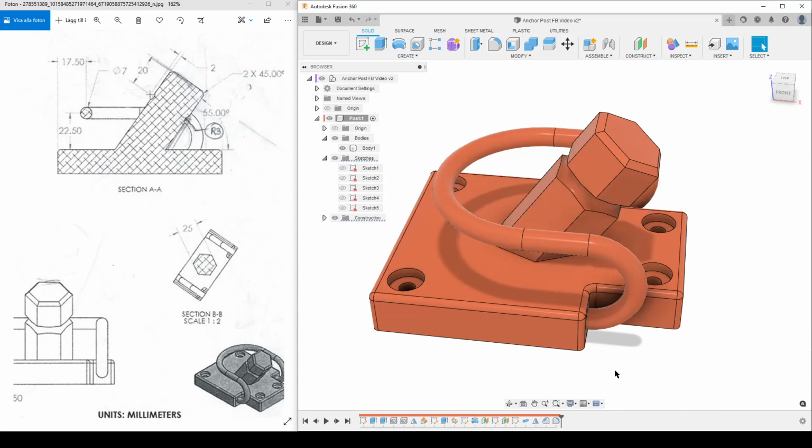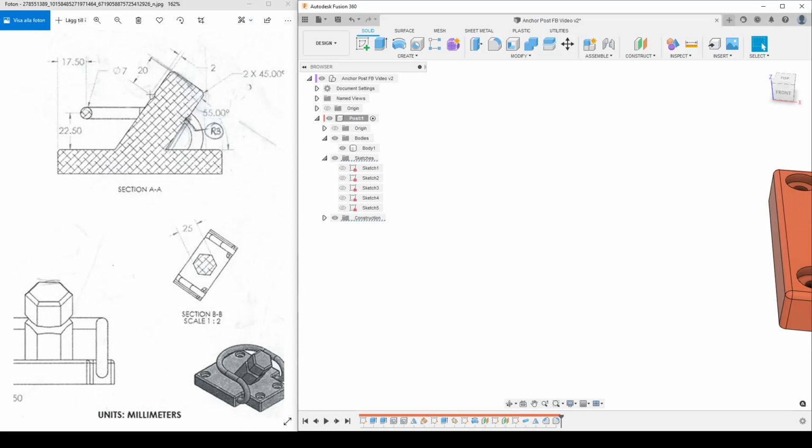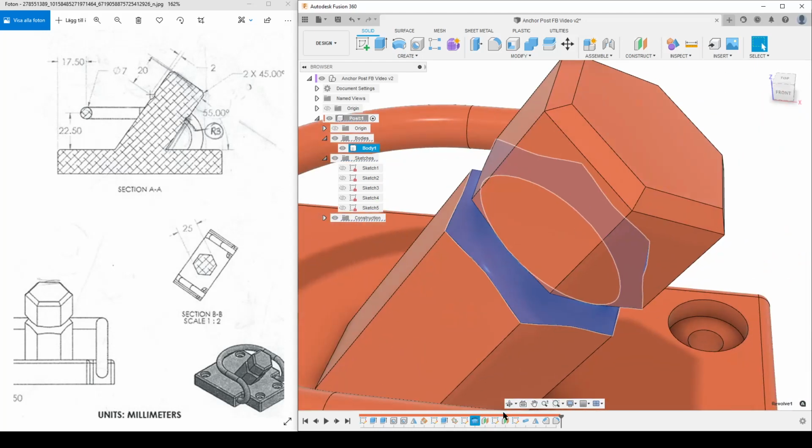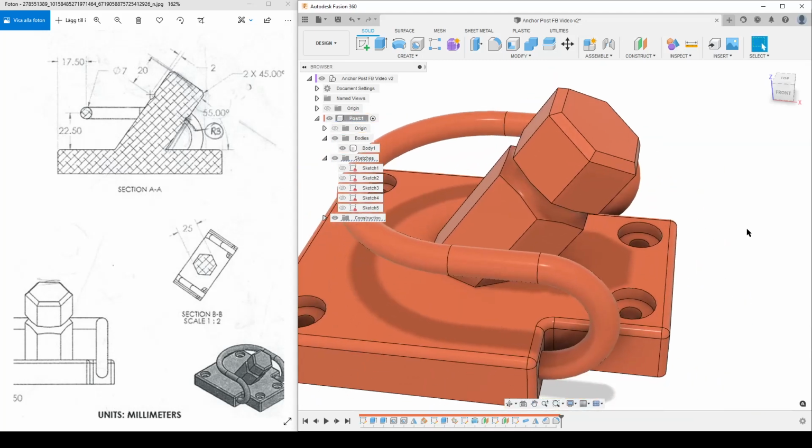And so that's right. That's another thing. If you can't find, you know, this is the Revolve command you want to change, let's say the model, you can't see the face. You can right click on a feature and select Find in Window. And Fusion will zoom in and highlight the face created by the feature or the solid body or what it is. So that's 2 ways of finding what's going on.